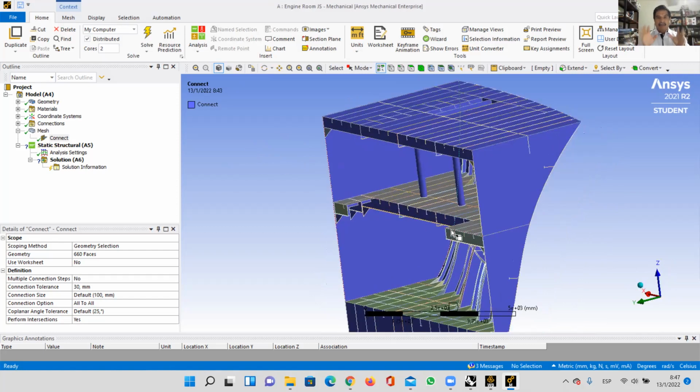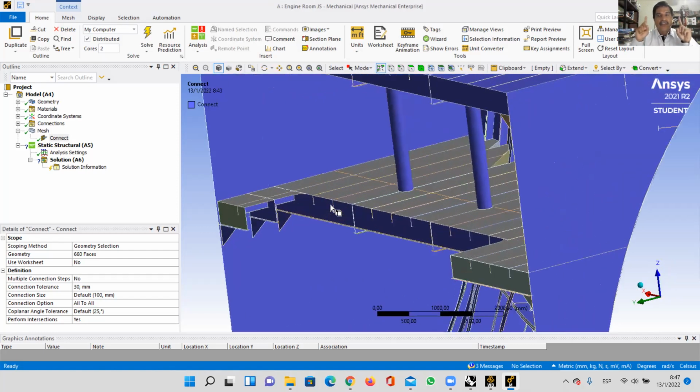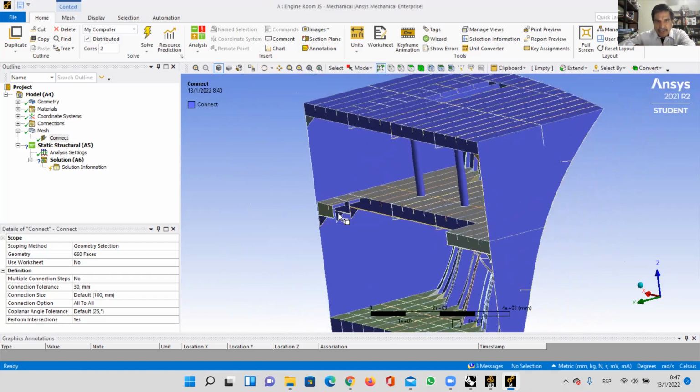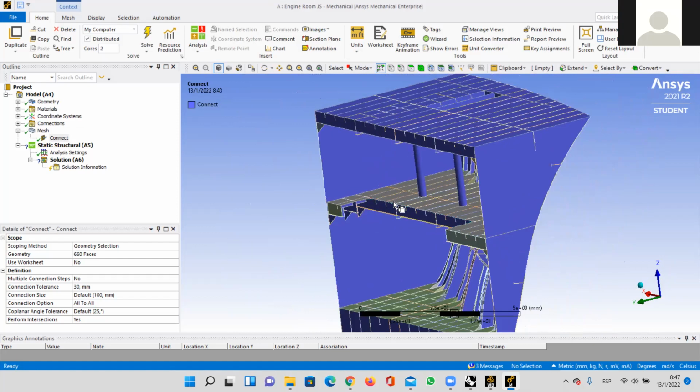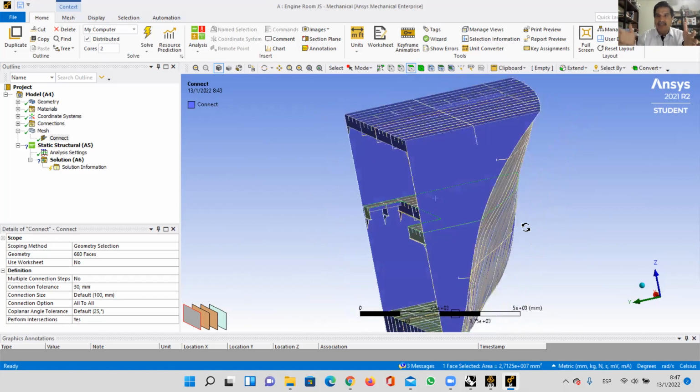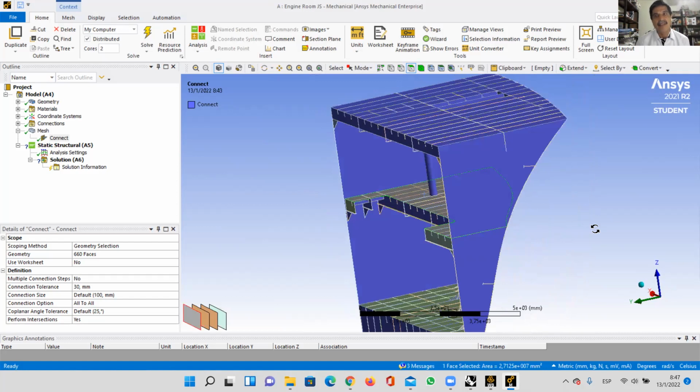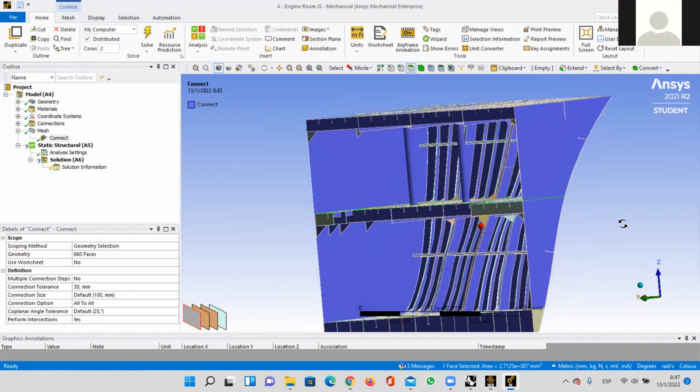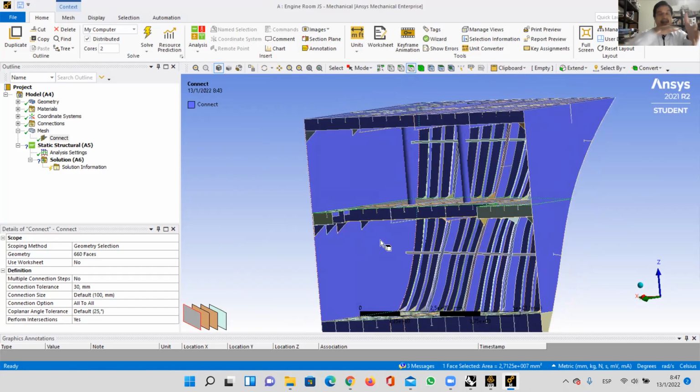like to see, for example, the full structure, and let's suppose that you concentrate on the intermediate deck, the one that you are showing here in this figure. Now, why don't you analyze that without any borders? Yes. But then analyze the whole thing and compare, and you can conclude how much the adjacent structure influences the analysis of the deck that you are analyzing. So analyze the whole structure with the deck and the original load.